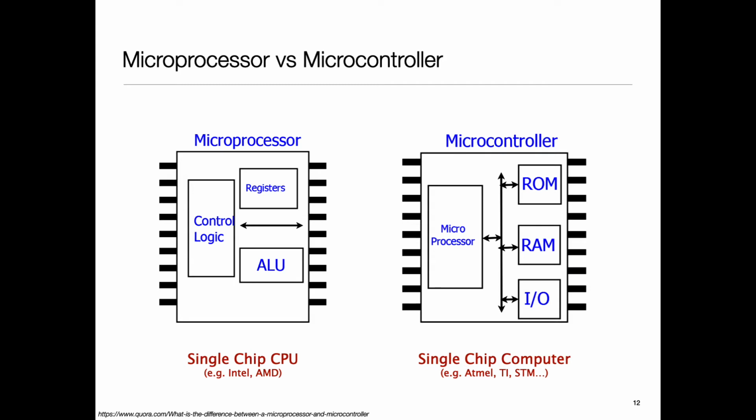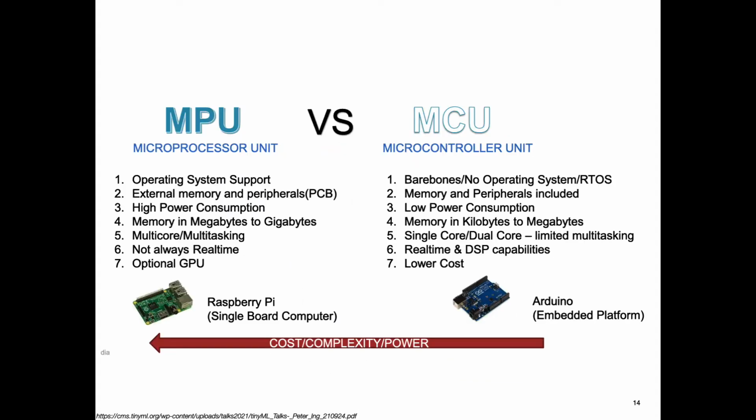So the difference between microprocessor and microcontroller is simply the level of integration, and the set of companies which are active in these marketplaces is different. Intel, AMD, these kinds of companies tend to be in the microprocessor regime, and the companies which make microcontrollers are setups like STM and Nordic, which in turn purchase the processor core from companies like ARM, or RISC-V as mentioned, and sometimes companies like TI with their own processor cores, and then they make these microcontrollers. So it's just the level of integration.